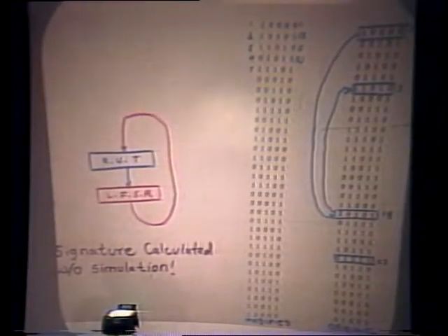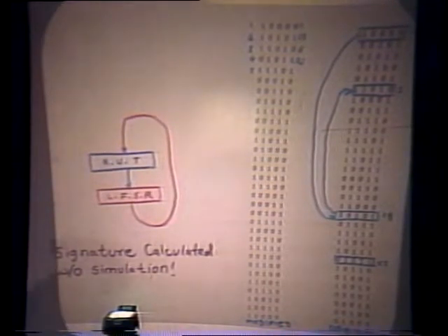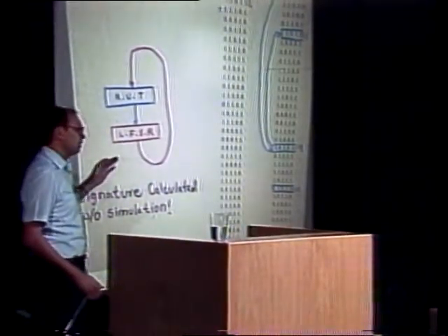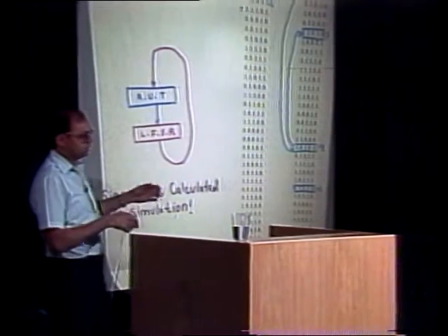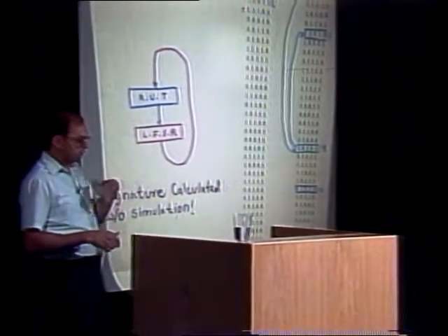So that takes care of guaranteeing the effectiveness of the test vector set. What about predicting the signature? Well, that is also easy, especially if you keep the sequence of operation fixed. That is, you pick a register, write a pseudorandom vector, read it back. In other words, when I say read it back, I mean read it back and compress it,